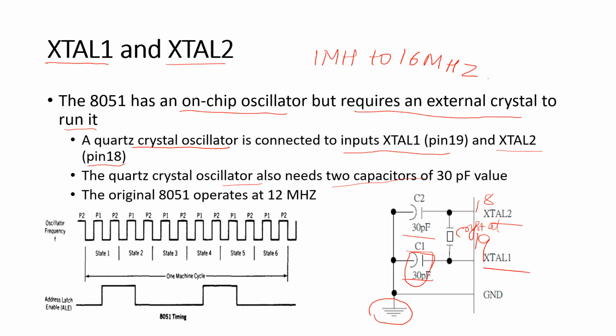It depends on the manufacturers, who make different 8051 designs available. Now the minimum frequencies imply that some internal memories are dynamic and must always operate above a minimum frequency, otherwise data will be lost.